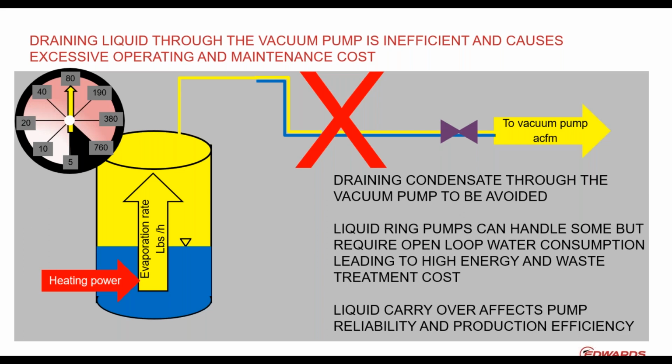Imagine your vacuum pump is now basically mostly bothering with the liquid and trying to re-evaporate it. So as long as you have liquid phase present, just try to separate it, and once the light boiling fractions are coming off, isolate it, not make it face the vacuum system anymore.